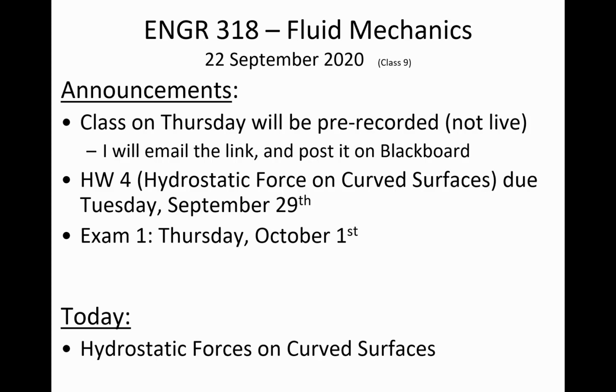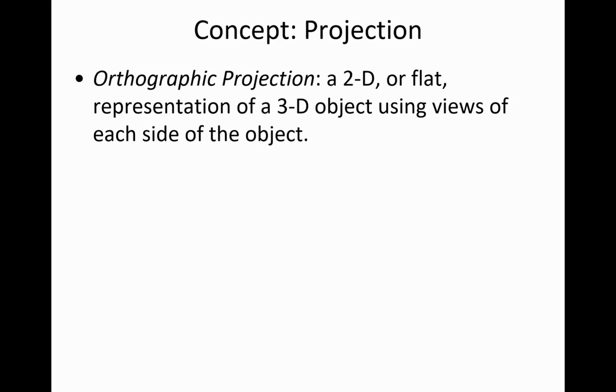All right, so in the last couple of classes, we've been talking about hydrostatic forces on flat surfaces, and now we'll translate some of those lessons that we've learned into computing the magnitude and location of hydrostatic forces on curved surfaces. And for us to understand how to do hydrostatic forces for curved surfaces, I want to remind you about the idea of projections. And this is probably something that you were exposed to previously in your CAD class.